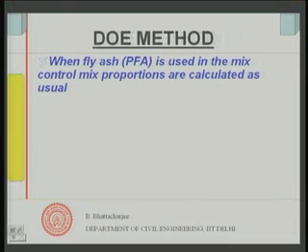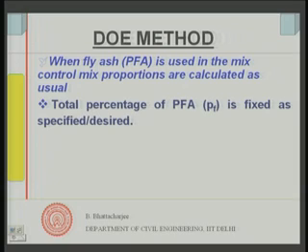Now, I think we can look into the application of fly ash in concrete mix design. First thing to do is that I must have a control mix made. That means, first I have a control mix without fly ash, right, and I first find out the control mix, that is a mix without fly ash. Then I have to take a decision, either it should be specified by the client, owner or anybody, or it can be my own decision to use a particular percentage of fly ash.